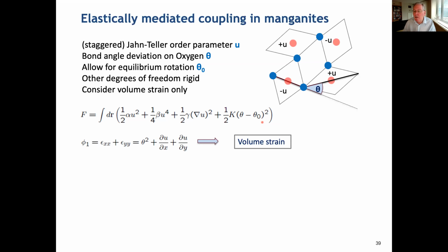And the reason they get coupled is via what's called compatibility relations for strain. So if I think of the volume strain, so basically just a change in volume, which I'll call phi in here, as just this two-dimensional model. One way of changing the volume, of course, would be to change this angle uniformly everywhere. The volume change goes roughly like the square of the angle. Actually, it's cosine theta, but for small angles, it's quadratic in this.